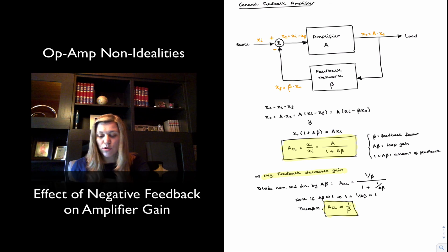And so using negative feedback, we can now design amplifiers that have a stable gain by using as the starting point maybe an op-amp whose open loop gain is not a very stable parameter. So we have decreased our gain, but we have gained in gain stability. So we have desensitized the gain from process parameters, process variations. And that's an important result.